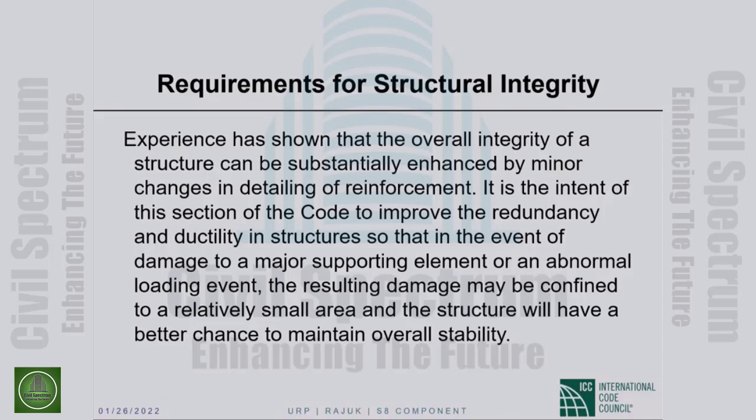So I will start with the question on torsion first. For a 4-leg stirrup, say 4 12 mm legs, can we assume the outer legs transfer the torsion and the inner 2 legs transfer only shear? No, not only shear. All 4 legs will carry shear. Outer legs carry torsion, and all 4 legs carry shear.